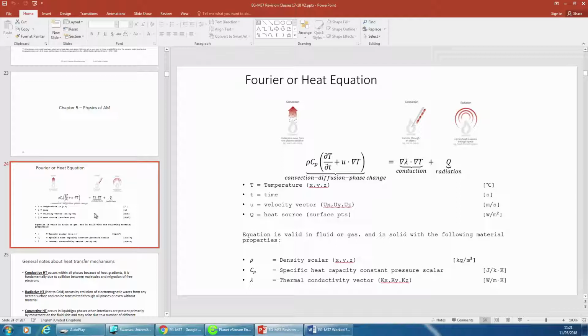There is quite a lot of wasted energy, so if you do compare, and that's something else we've had a look at, if you compare directly melting a metal through something like induction melting, you might end up with maybe 1 kilowatt hour per kilo of metal melted. When you're using a laser to melt the same amount of material, you're using 20 times that or more. And part of the problem is the laser has to be stabilized and thermally cooled all the time, so for our 200 watt or 400 watt lasers, we'll have a 1 kilowatt chiller continuously cooling the laser while the laser's doing the work. So not only does the laser use the energy to melt, but it also needs to be cooled at the same time.